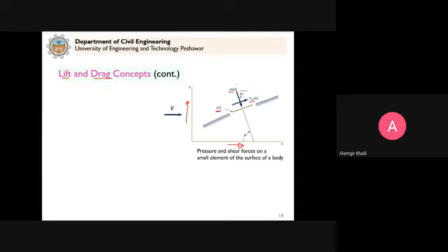So we resolve these two types of forces, such as the pressure and the shear forces, on a small element into components, taking the orientation. So for this given setup, we come up that the differential force dF acting on this area dA in x direction is equal to P dA cos theta and tau_w dA sine theta, both in the positive x direction, so they carry positive sign.